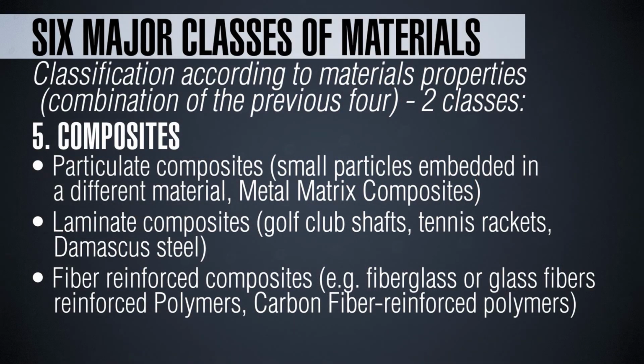Laminates are a very diffuse kind of composites. So you have, for example, in the case of wood, layers of wood which are aligned, keeping the direction of the fibers in different orientation, layer by layer. This will increase hugely the isotropic properties of the final laminate. Or we may think of placing together a piece of wood and a piece of polymer. That would give you enhanced properties, enhanced resistance to water, for example, or to scratch.